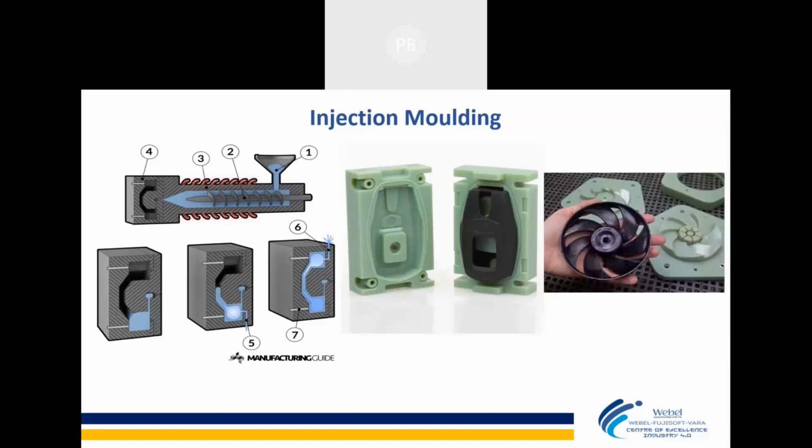After doing the trial of 40, 50 pieces, once they get satisfied that the mold dimension is completely okay, this is the perfect dimension for my mold and all the testing is completed, then they go for the metal mold, which will be used for their lakhs of pieces. So 3D printing is now coming up as an option for T0 production molds, which are also known as soft tools. A soft tool can be made directly by 3D printing. So in injection molding, 3D printing is playing a very vital role, and is coming up with T0 production-grade molding.